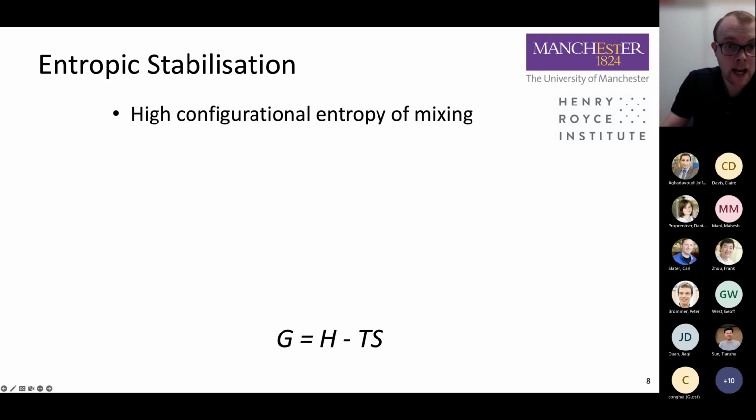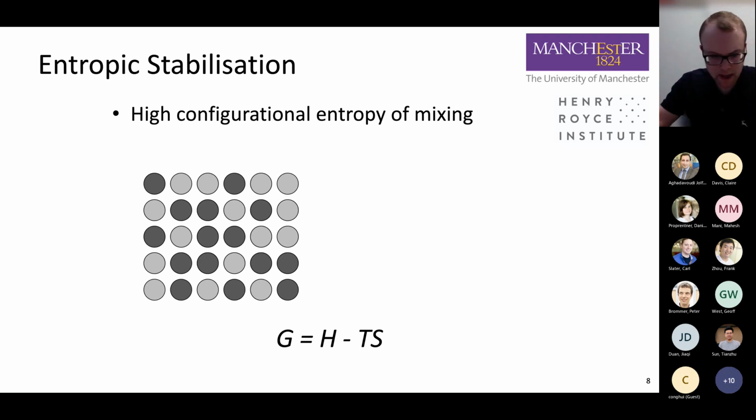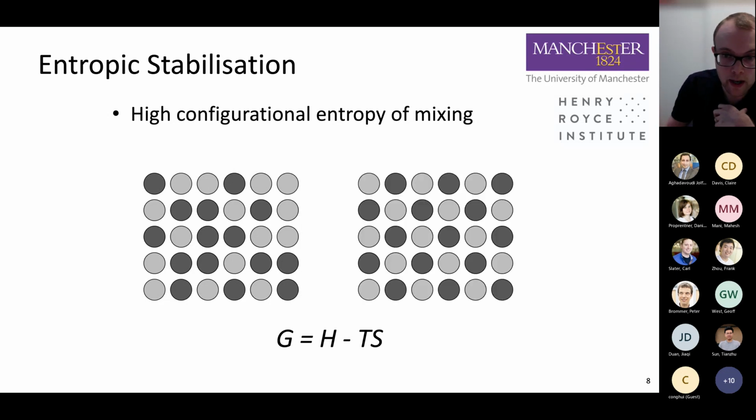Okay. Some examples of extreme cases are where we add 5 elements each at 20 atomic percent, and we generate quite high entropies of mixing then. And the idea is that the reduction in Gibbs free energy that you get from that increase in entropy outweighs the driving force to form intermetallic compounds.